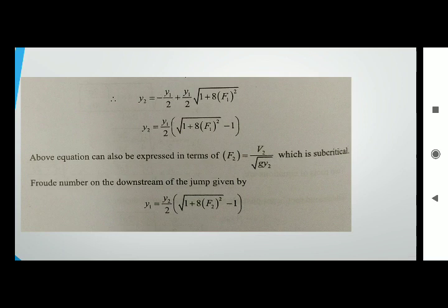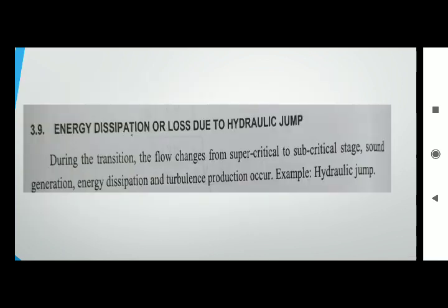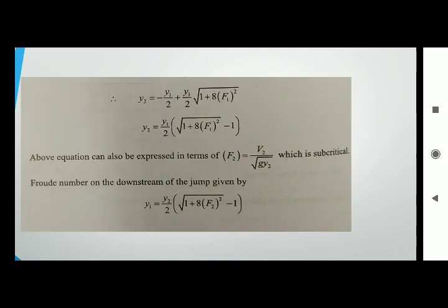Now let's discuss energy loss. As I said, the flow changes from supercritical to subcritical, and this change occurs with energy dissipation. This is a very important thing. If I know y1 and y2, then the depth of hydraulic jump is y2 minus y1.